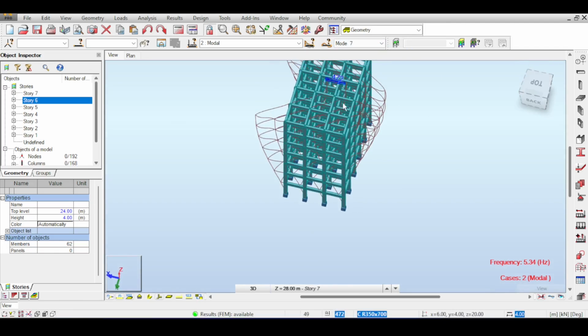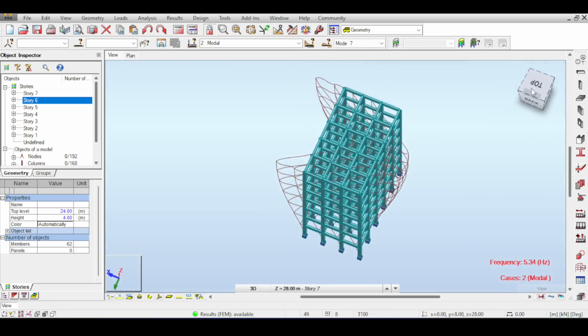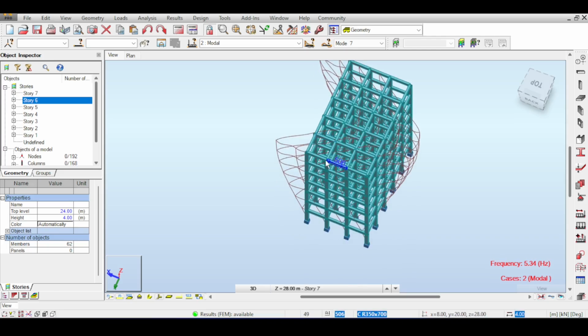Now, this is really strange. And this is where things become a little bit iffy, especially for our subscribers. So you can see that the modal calculation resulted in a structure where the first and second layers of columns bend in the strong axis to the left, and the rest bends in the right.